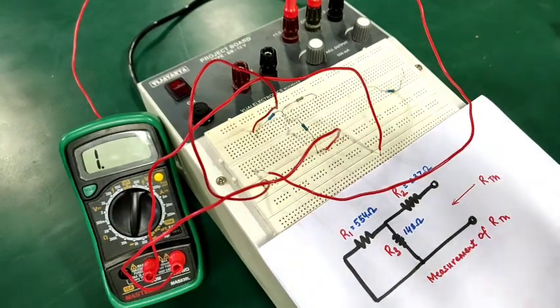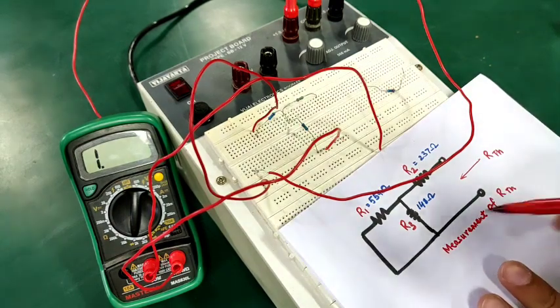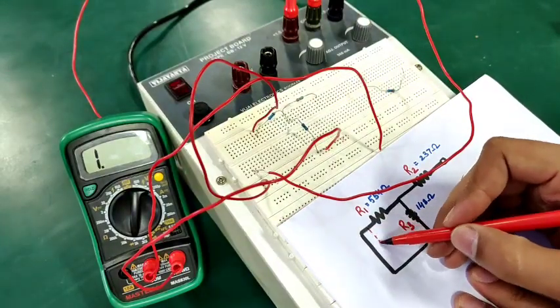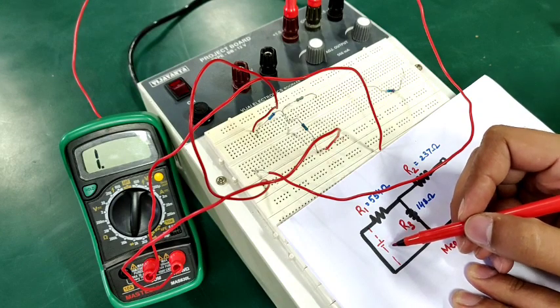So moving on to our next step, which is step number 5. We are going to find out another important parameter, which is Thevenin's resistance. So what is the procedure for calculating Thevenin's resistance? Firstly, you will remove your load resistance, and secondly, you will replace all the sources in the circuit with their specific internal resistances. So what we did here, we removed the voltage source which was initially present here and replaced it with a short circuit.